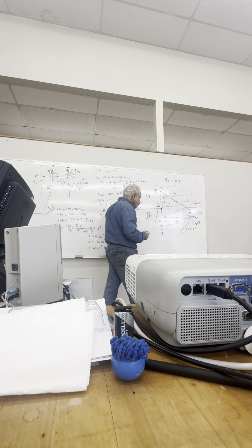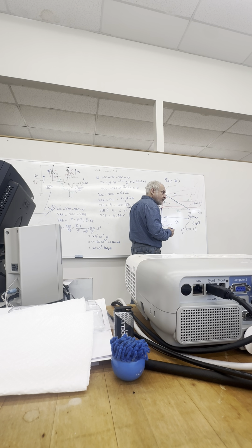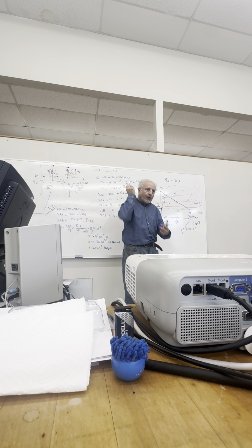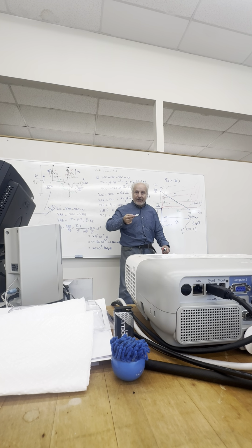Is the 0.7 volts the avalanche point? It's not an avalanche. It's the, what do they call it? The elbow. Elbow. Yeah. Right? I'm trying to think from French to English. It's the elbow. Avalanche is in reverse when we're using the Zener region. Does that make sense? Mm-hmm.